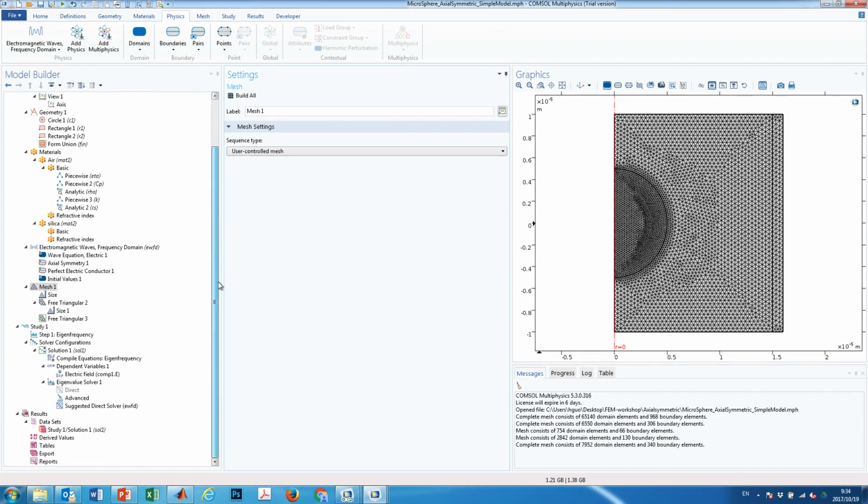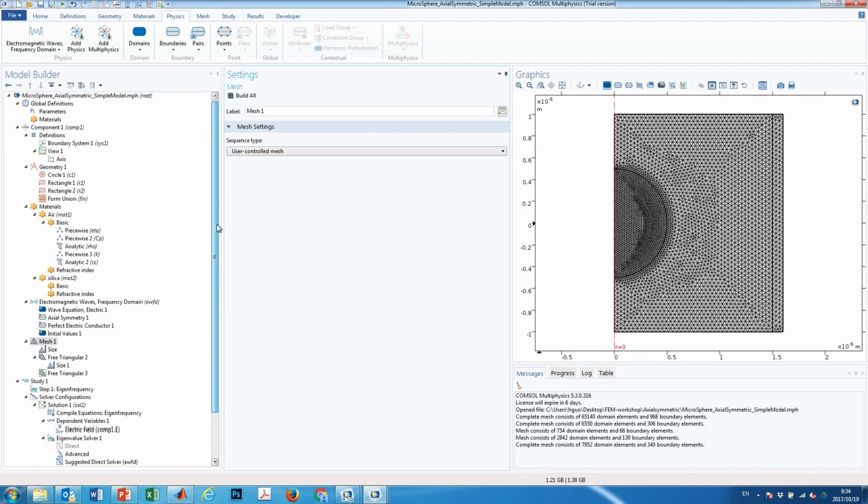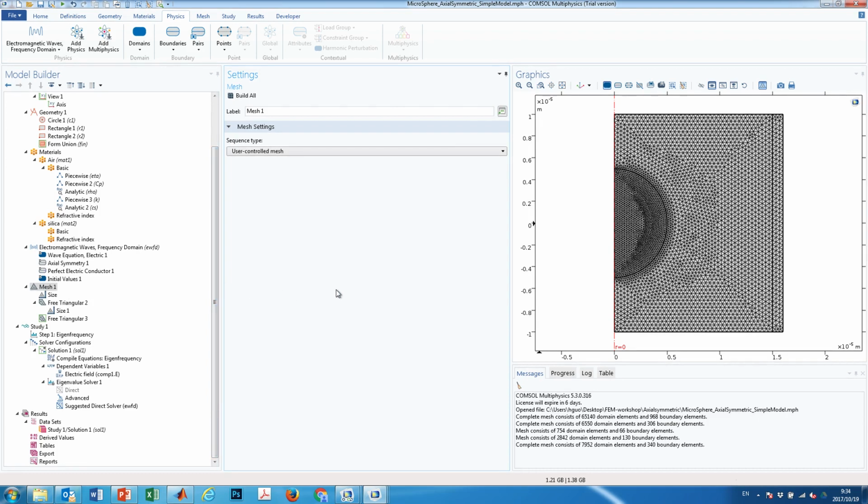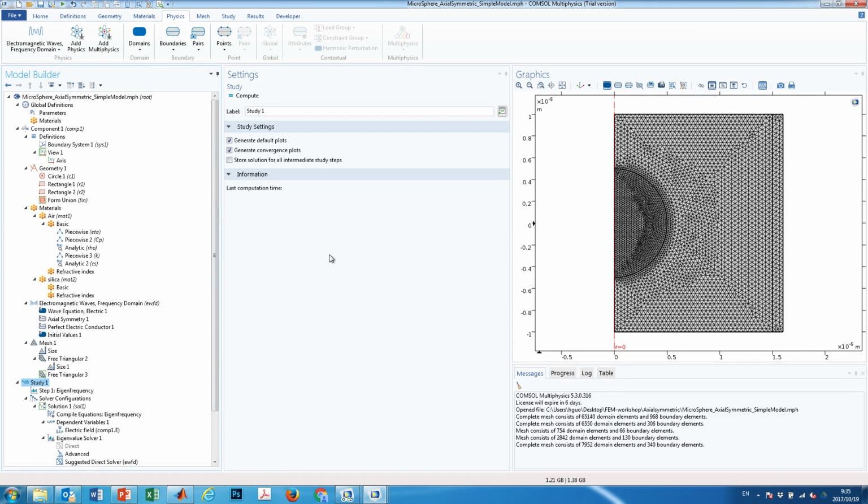So this is just a very initial step to let you know you have different options. You can let the system define it because it's physics-controlled. You can also manually configure different levels of mesh at different areas. So I think in this way we can try to compute. Sorry? The boundary conditions? We let it be default in this way.